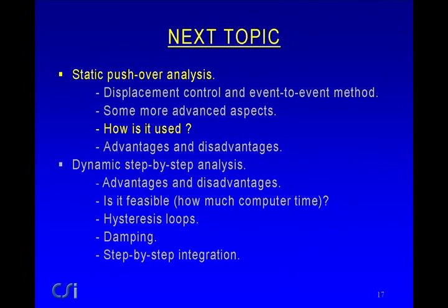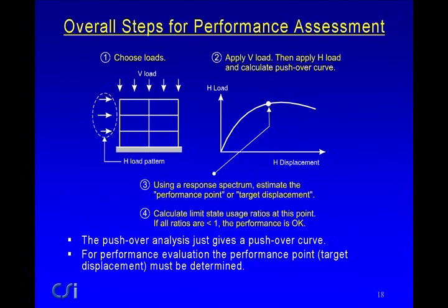And we used this slide before. Step 1, you choose the loads. Step 2, you get the pushover curve. And then step 3, using a response spectrum, you estimate the target displacement. And step 4, you calculate limit state usage ratios at that target displacement.